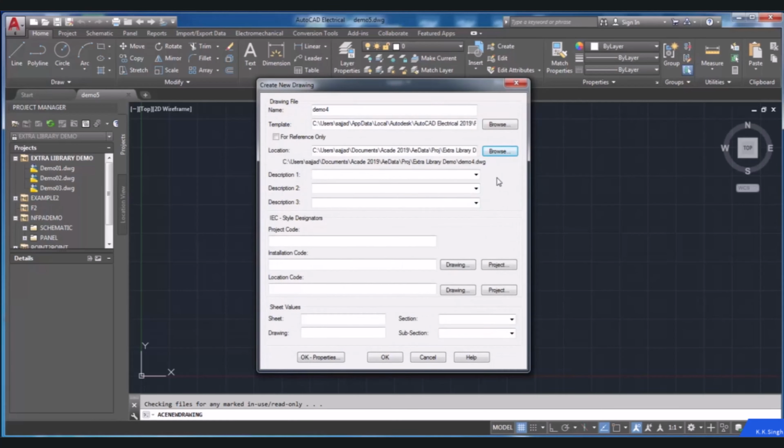Notice that you cannot create identical drawings at the same location. You can use the description edit box to insert a description for a drawing. If you entered a description for earlier drawings, you can select a new description from the drop-down list.